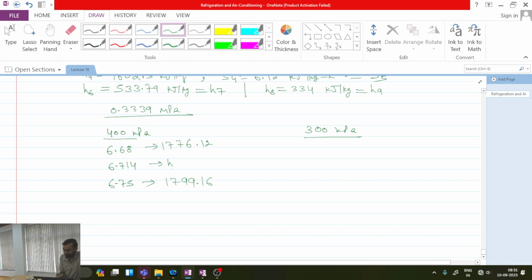You need to calculate enthalpy at this point. So enthalpy at 400 kPa is how much? Tell me. 1799. Y2 minus Y1 divided by X2 minus X1 plus Y1. Okay. So how much is it? Yeah, 39. Yes, correct.